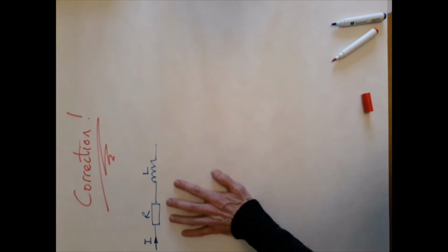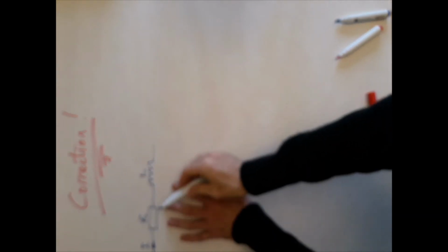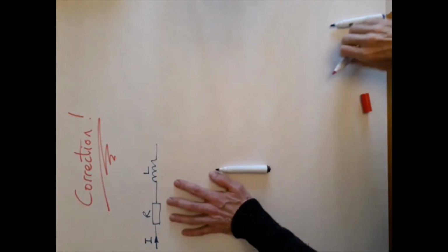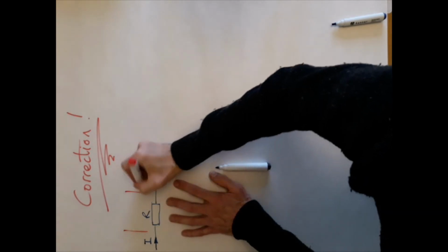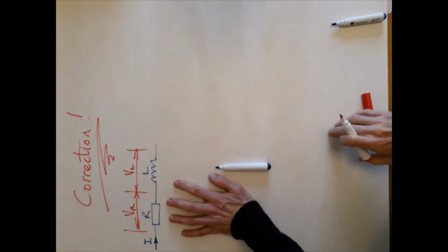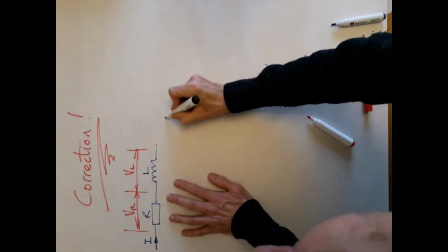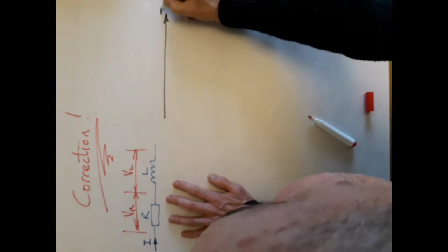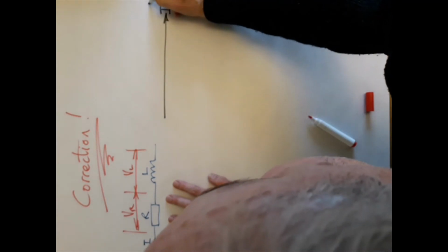Where you see the series circuit, current is common to the circuit, and we have the potential difference, or voltage, across each one, VR and VL. Current is common, so current is the first phasor.